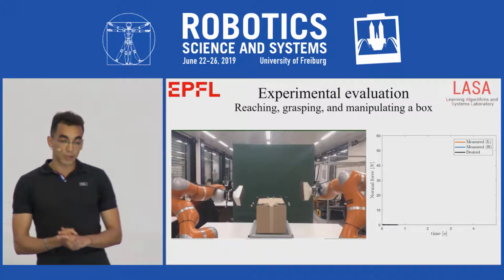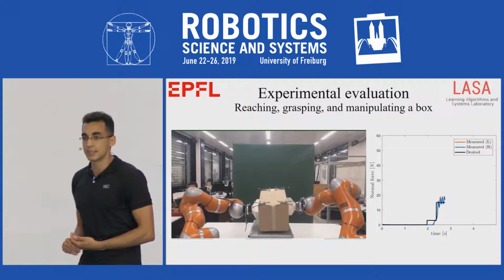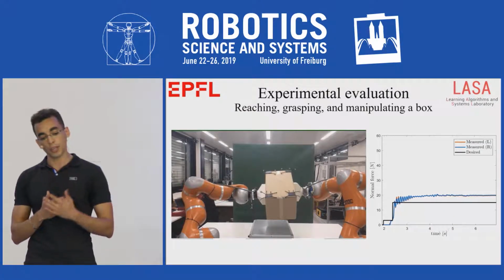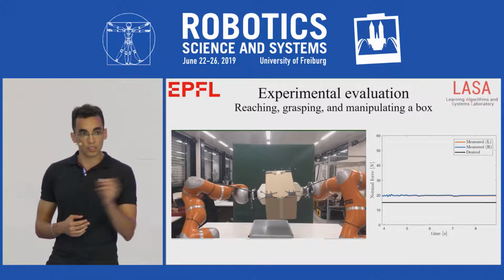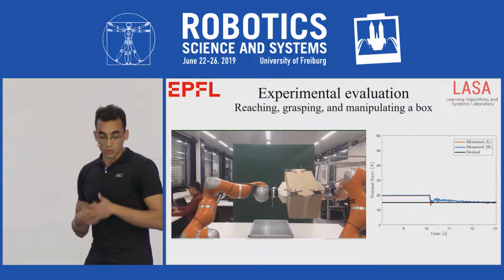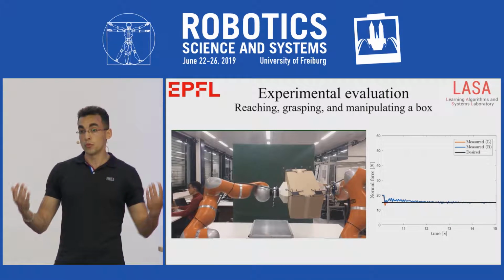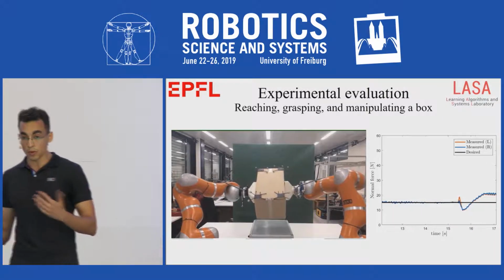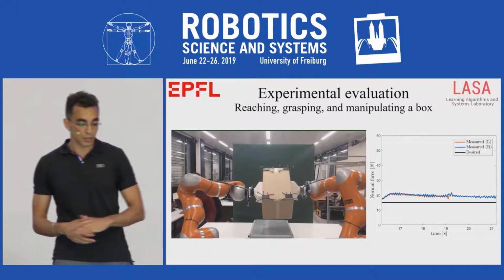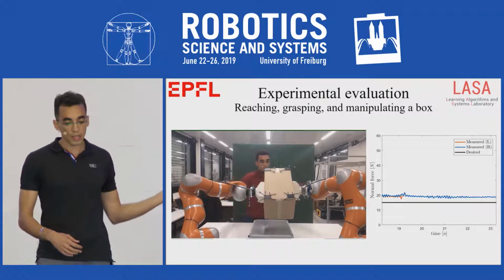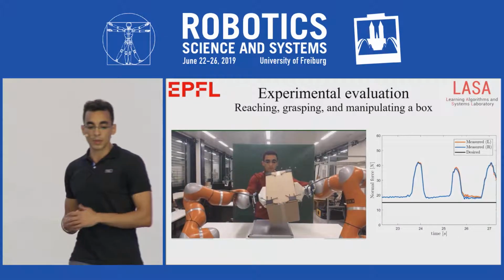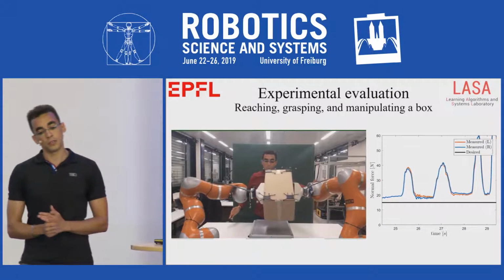And here is a similar video where this time the two robots reach, grasp, and lift the object to a predefined location. Then the human can change this location through a graphical interface. As before, the robots can move with the object while maintaining the grasp, but at the same time we have a system that is compliant and stable, as the human can come and apply large disturbances to the robots, which comply with them and try to maintain the object grasp at the desired location.